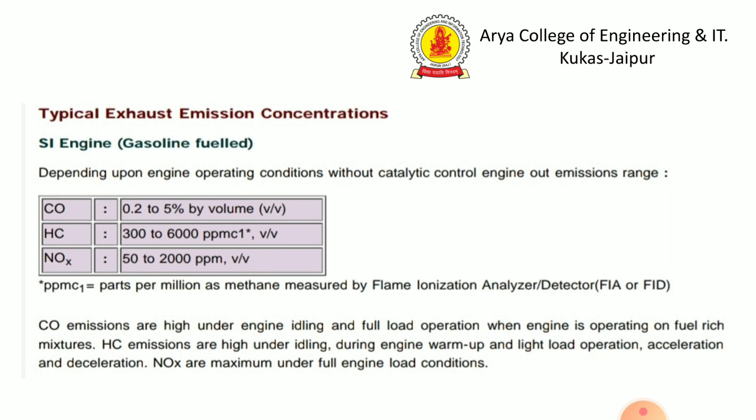The CO emissions are higher under engine idling or full load operations, when the engine is operating on fuel rich mixtures. HC emissions are higher under idling, during engine warm up and light load operations, acceleration and deceleration. NOx are maximum under full engine load conditions.